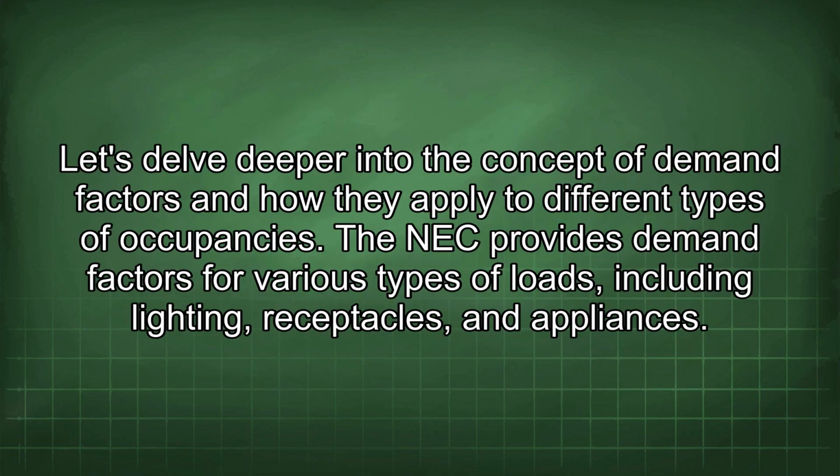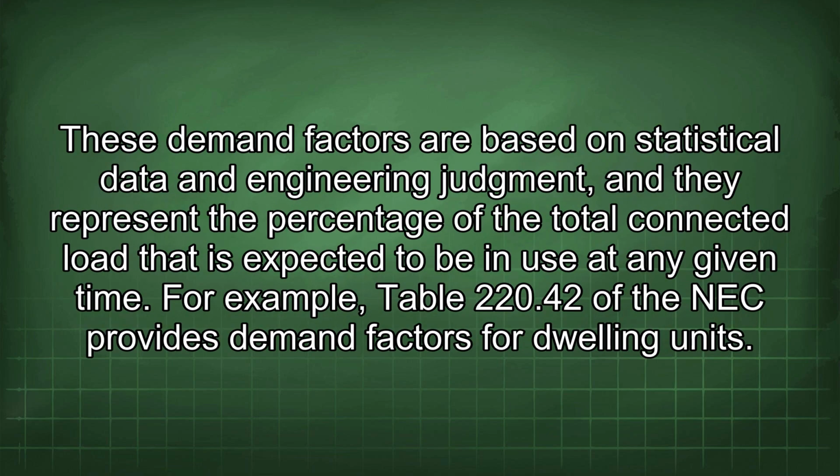Let's delve deeper into the concept of demand factors and how they apply to different types of occupancies. The NEC provides demand factors for various types of loads, including lighting, receptacles, and appliances. These demand factors are based on statistical data and engineering judgment, and they represent the percentage of the total connected load that is expected to be in use at any given time.